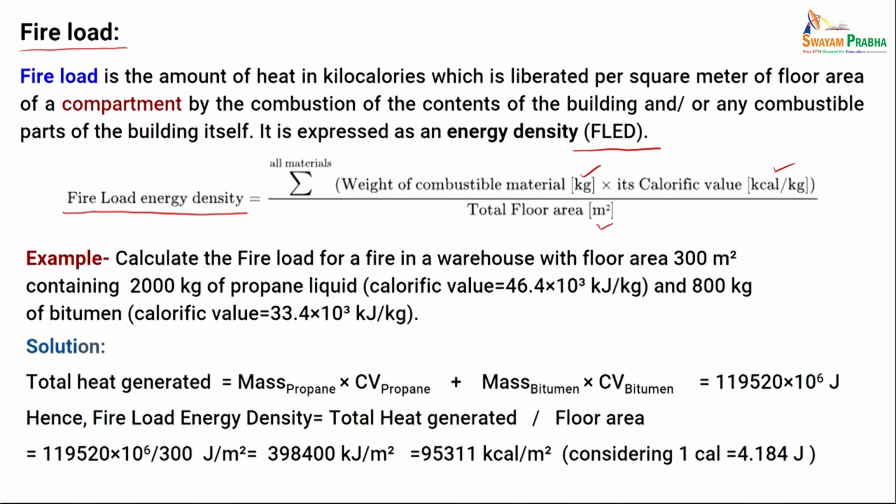So, if we look into a very small problem over here: calculate the fire load for a fire in a warehouse. Now, you see it is a warehouse where not much of human being is there, with a floor area of 300 meter square, containing 2000 kg of propane liquid whose calorific value is given, and 800 kg of bitumen whose calorific value is given. The solution is given over there.